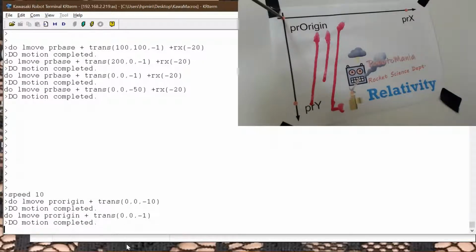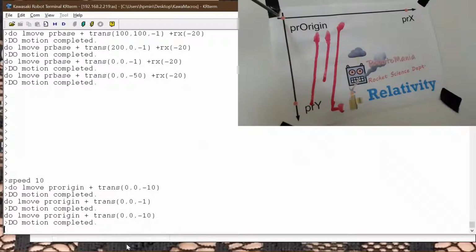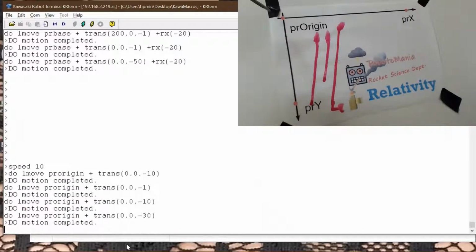And from this point onwards, I will retract once again. 10 millimeters. Because we will be moving on a plane which is not orthogonal or parallel or anything to the robot, just a plane randomly positioned in space. I will ask a little bit more distance, more clearance, right? And I will move to check my X position, the way it is defined. X, okay. Let's see what gives.